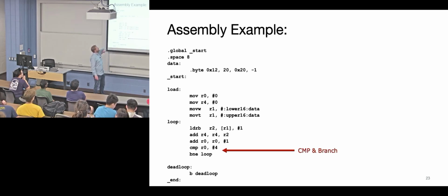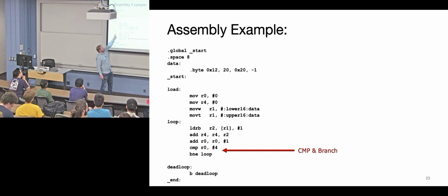Those are put in sequentially. So which byte does LDR byte load? Well, what's the address? If that is going sequentially, the first address is going to denote that. Remember, this is byte addressable. Each one of those things has a different address, and you're going to load in that byte and put it into this register. It's going to do that first byte, then increment the address, next byte, increment the address, next byte, as it places that into memory. Does that answer your question?